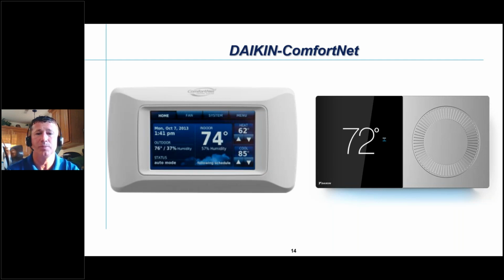If we look at the progression of Daikin, Daikin had been using the CTK04 thermostat, which is on the left, and they are now moving into their own proprietary thermostat, the Daikin 1 Plus thermostat. And when they were talking about fully communicating in the one on the left, it didn't have contact switches. It had to use auxiliary contacts either in the furnace or in an electronic interface module to be able to make switches, because we still have appliances that need to be switched.